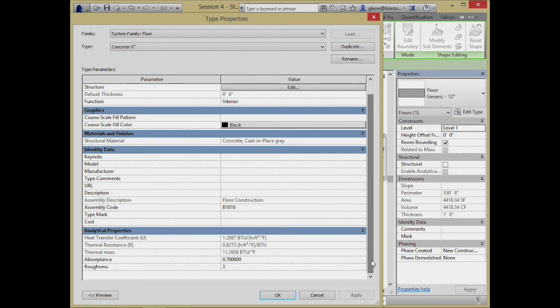Which is why you might wonder, as you wander around inside the Y2E2 building and see all these polished concrete floors, why they're all concrete. It's not just strictly that it was a cheap surface and a very inexpensive way to do it. It actually has this really good thermal property. So, going back to the Y2E2 building, what happens if you take that incredibly nice thermal mass and you put a whole lot of carpeting all over it?